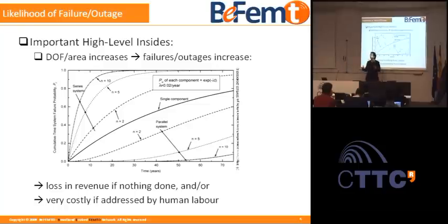The probability that your system goes in outage or that your system fails is essentially directly related to the number of components you have, okay, and the probability of a single component going in outage. So I'm taking one of the typical slides from this operational design. You plot the probability of failing of a single component versus time in years. Having a single component, and a component can fail with a certain failure rate they are given there. It's just an example to give you an idea. That probability over years goes up.